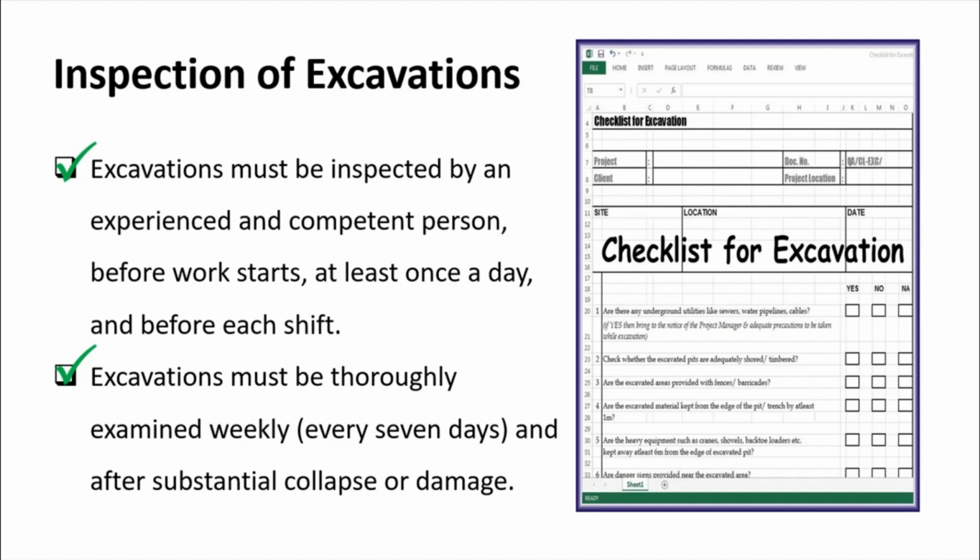He should check all of this, including the shorings and the condition of the soils on the excavations. So every 7 days, or after the collapse or damage of part of the excavation.